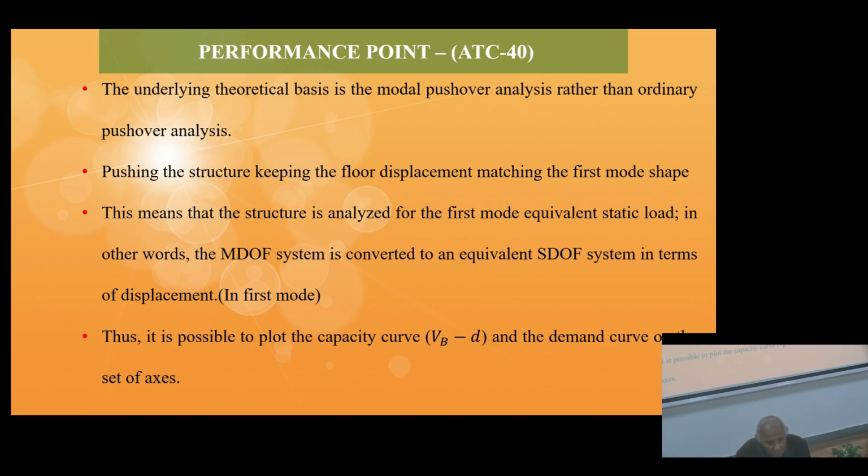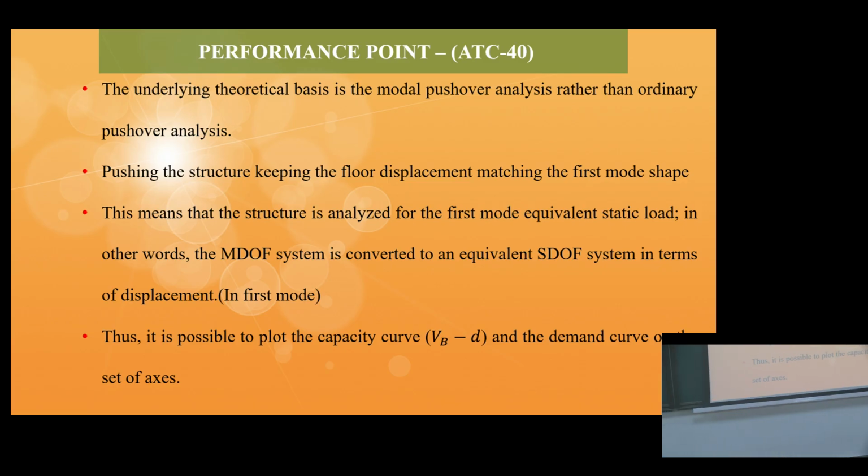Once it is done, then you can convert the entire structure into a single degree of freedom system. Okay. And once you have converted into a single degree of freedom system, then the things become simple. Okay. You can plot it into SASD. Now, the normal mode theory in dynamics, you will see that it is doing that.